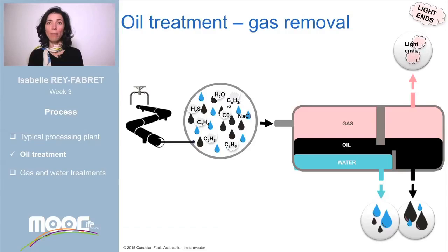For that, the amount of evaporated oil during this part of the production chain has to be reduced. It is necessary to remove most of the dissolved light ends from the effluent. In practice, stabilization or degassing is the process which removes dissolved gas from the crude oil.